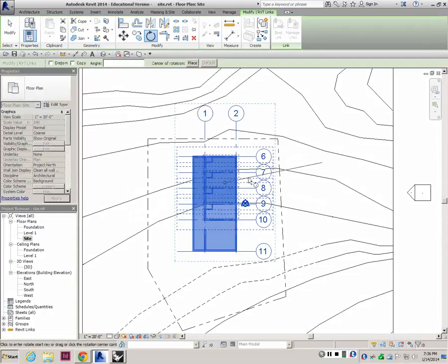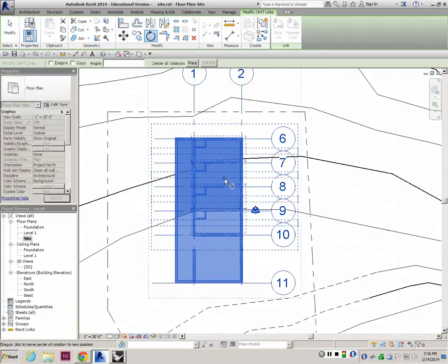And in rotate, you basically have an anchor point and a rotation angle. And this is used as a reference. But if you want to rotate it according to some value or direction, you could move this rotation anchor point any way you want. So let's move it to this corner. Then I want to use this endpoint as reference.